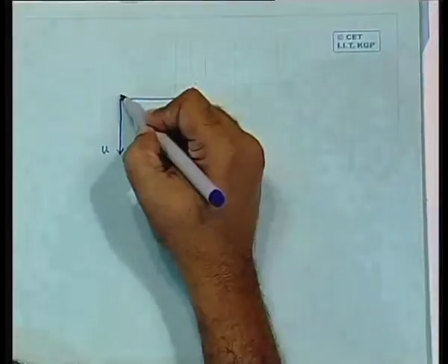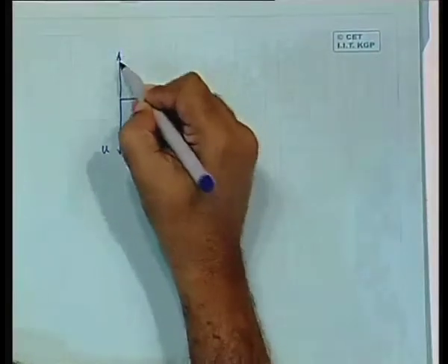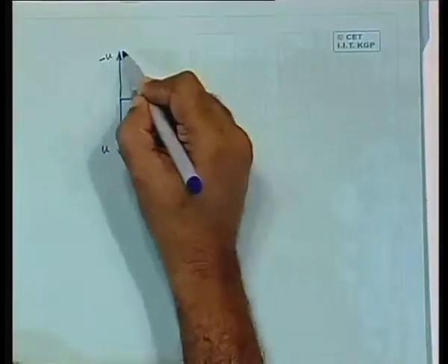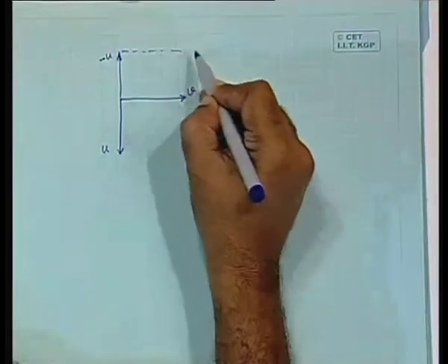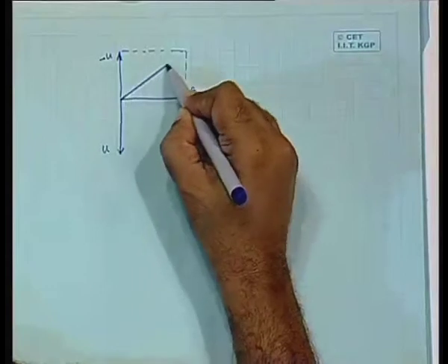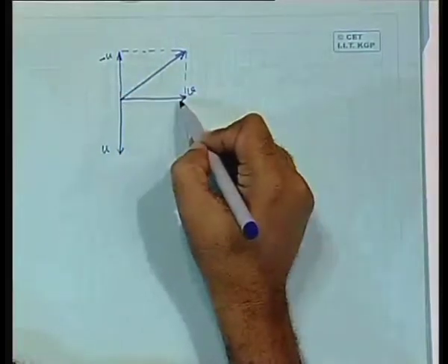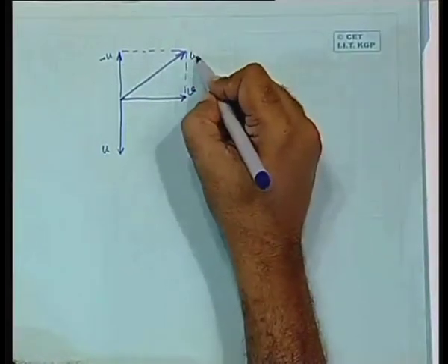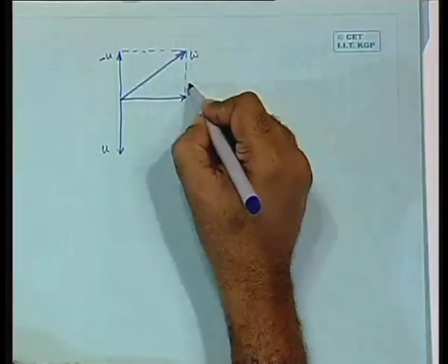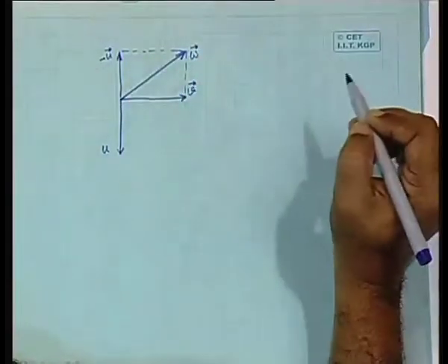As a result, we will construct the parallelogram like this, minus u, and in the last picture we drew a general picture, but now we are referring specifically to the wind turbine, in which these two vectors are orthogonal. You have the w here, okay. So this vector added together gives the w, or the relative wind vector.